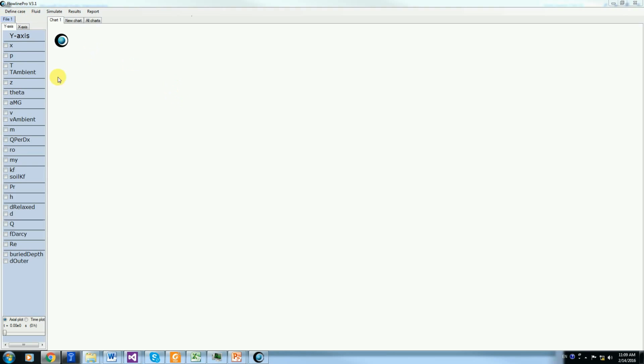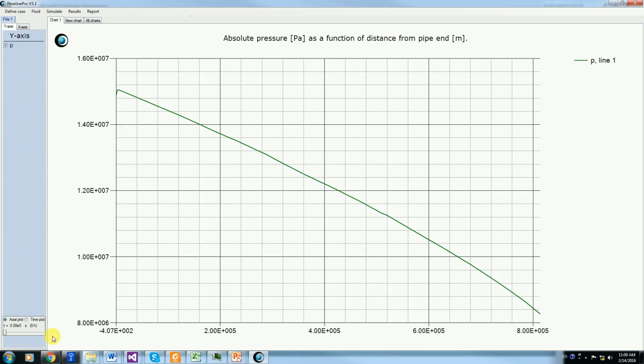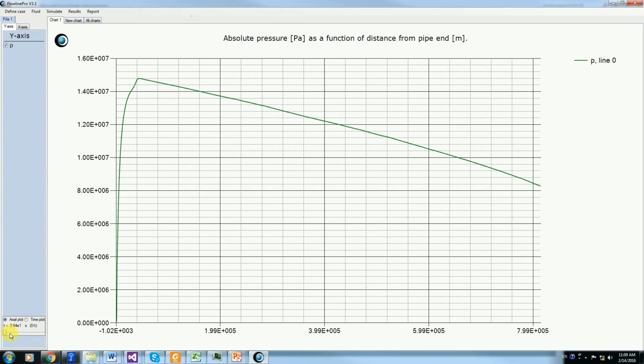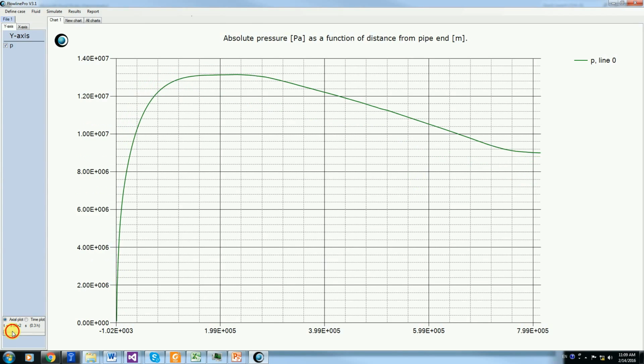Okay, here we go. Let's look at the pressure now. Obviously the pressure at the beginning is as before, but then a very short time later the pressure goes down to 1 bar only at the inlet, and it stays high in the rest of the pipeline for a while at least. But as time goes by, this has an effect everywhere.